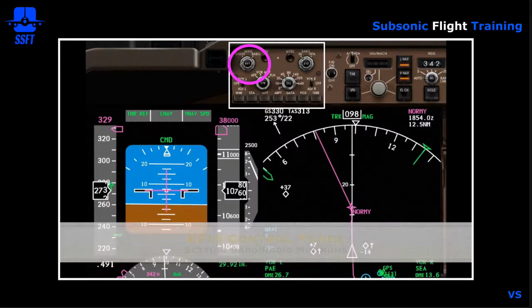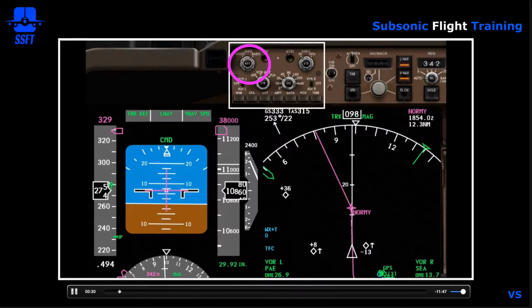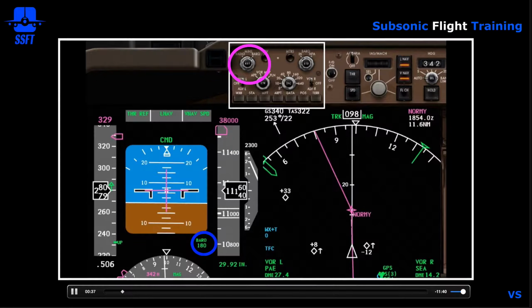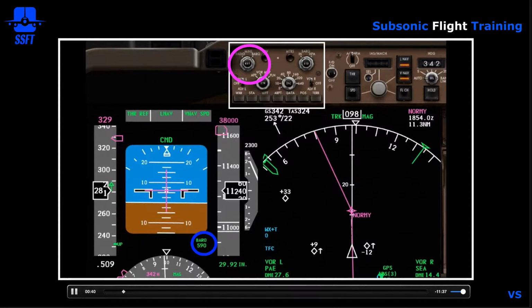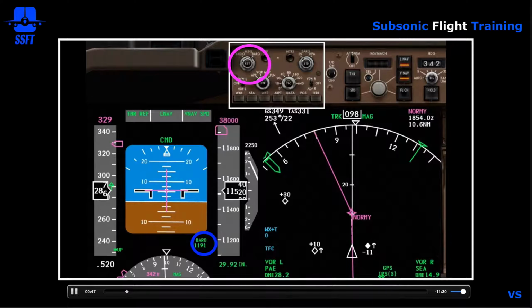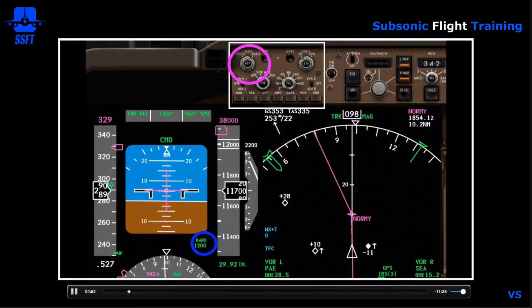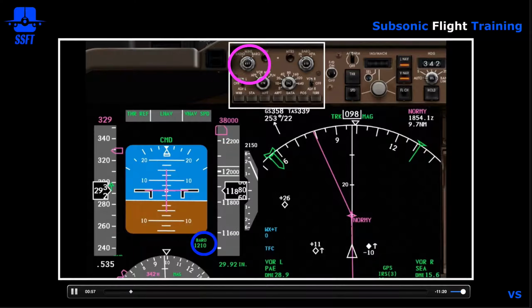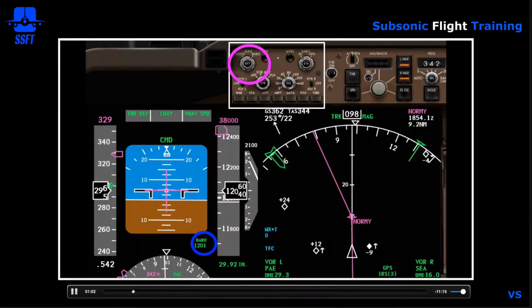We're going to look at setting the baro and radio minimums. The outer selector, which is located right here, is used to go back and forth between baro and radio. We're on baro right now. The inner selector, which is being turned, is setting our minimums. We're going to set 1,210 feet. For the minimums, you'll notice when you slow down, we get single-digit increments. If you go fast, they're in increments of 10. The faster you go, the faster they'll spin. So we've got minimums of 1210.